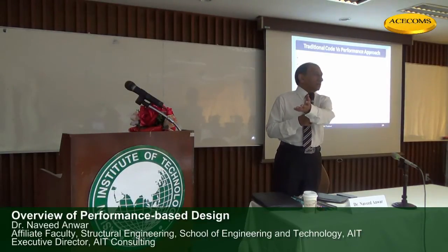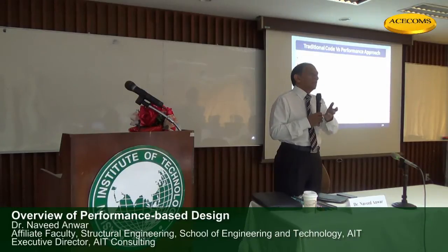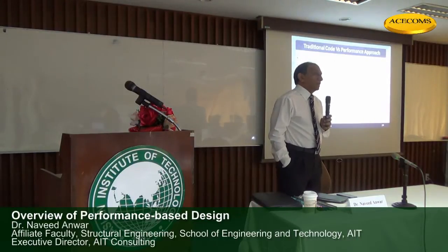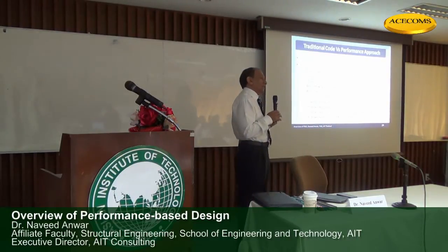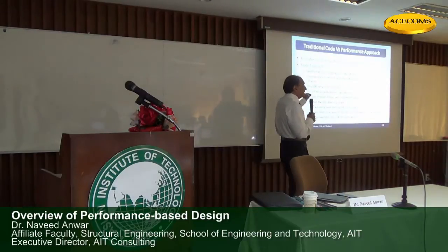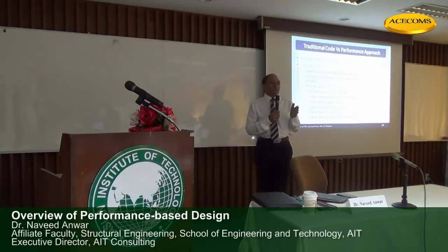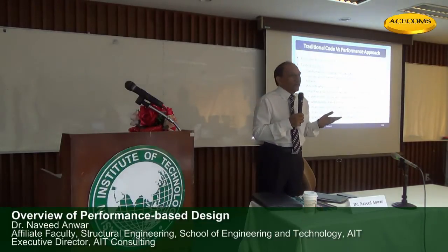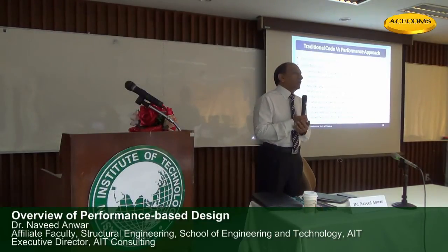Because maybe this beam is not the primary beam. There's a shear wall close to that, or another big beam which is taking the load, not this beam. So many questions arise, and if we simply blindly follow 100 millimeter spacing for every beam in the structure, well, we are following it, but we don't know what the outcome is.